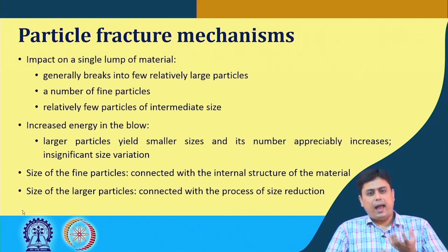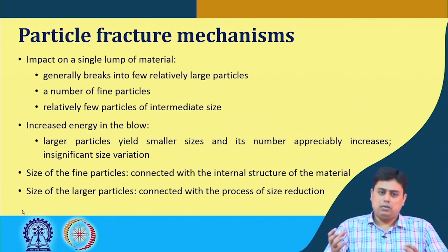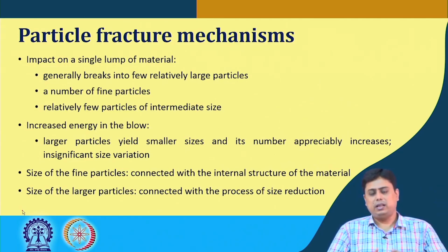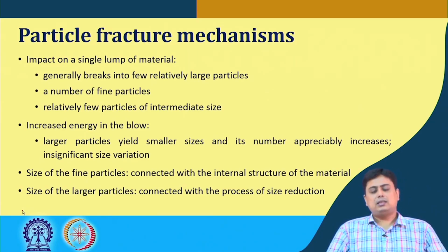So, initially you had a rock with a certain impact; it goes into several large particles, fewer intermediate size particles and even fewer fine particles. We increase the intensity of the blow. What happens? These large size particles will create more and more finer particles. So, the number of finer particles will increase, but the size of these finer particles will not change significantly.